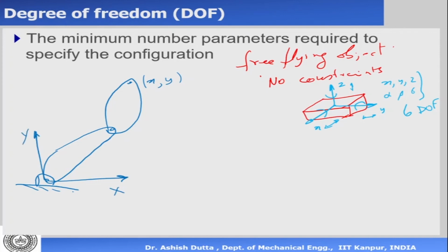Now about the z axis, this is my z. It can rotate like this. About this z also it can rotate like that. This is my z, right? So there's a theta 1 there, there's a theta 2 there. Now with theta 1 and theta 2, if this is my L1, L2, I can find what is xy, right?